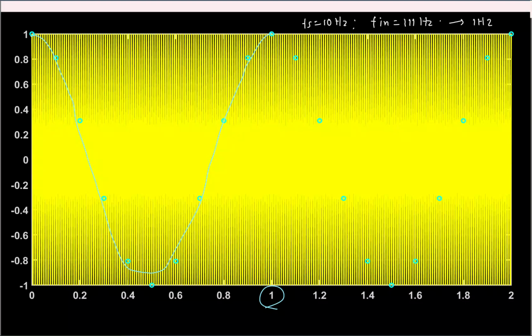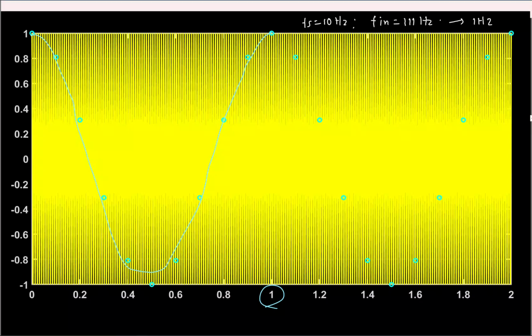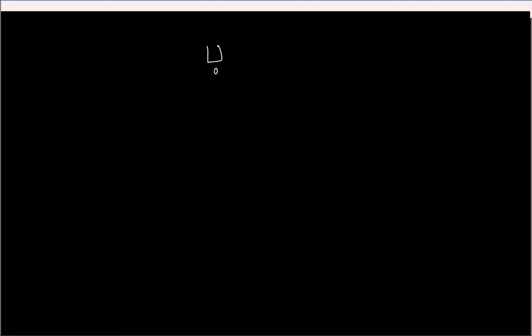And of course, a more cool demo of aliasing is in photography. You would have seen cases where the rotors of a helicopter don't move at all, or videos of water dropping from a tap, where it looks like the droplets are moving up. It's the same thing: water droplets are falling down, and videos are basically samples of multiple images played at some rate. If you don't capture fast enough, it will look like first this droplet is falling, and then you might capture an instant where the droplets are here, so it will look as though the water is moving up.